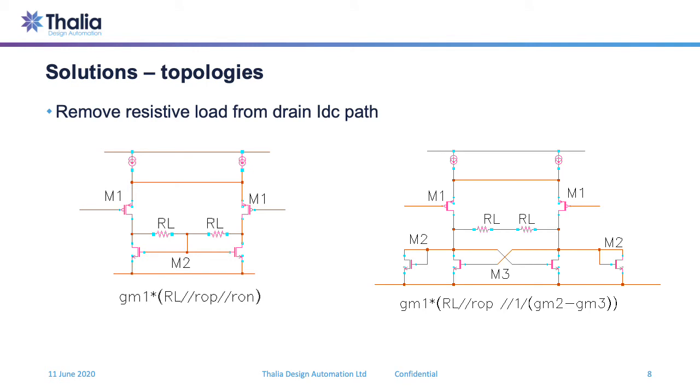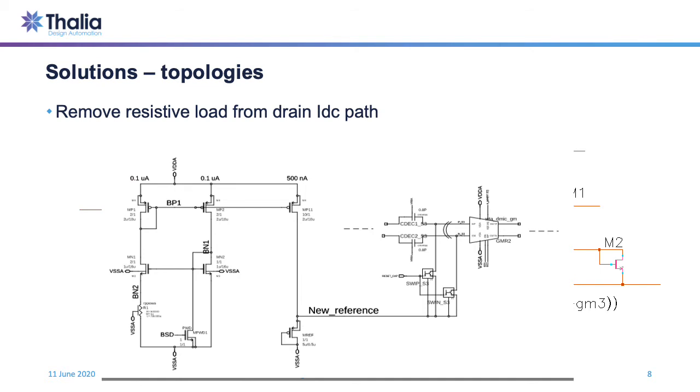What we saw in the previous slide was that the VD-SAT between the base and the target technology differed by about 5x. Obviously, this difference was the reason why the devices went into the triode region rather than being in saturation. The topologies are listed on the screen. There are three, essentially put together to recover the lost headroom. I won't go into the detail on the functionality of these topologies, but the motivation was to recover the lost headroom.